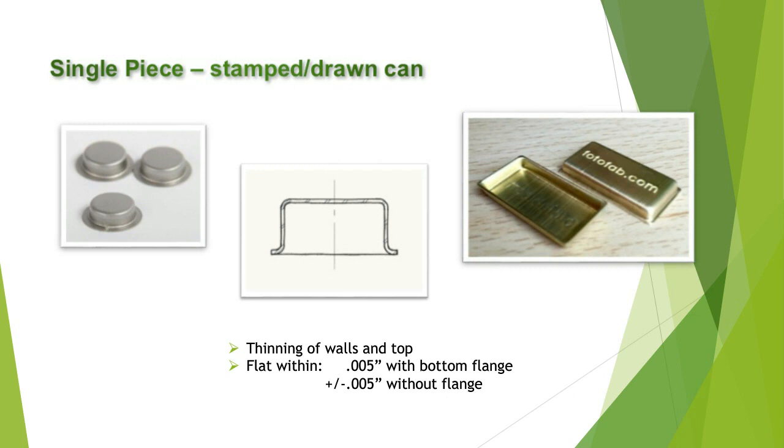Since it is sort of full thickness bend technology, you're always going to have an inside bend radius that you have to account for in terms of making sure that the part's going to fit around your components. Usually these things are available with or without a flange across the bottom. That formed flange that I've drawn there is shown in the photographs.